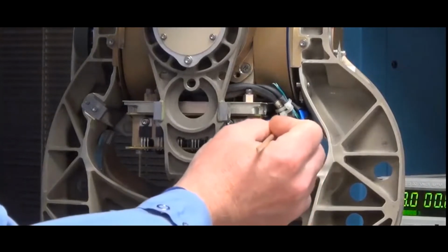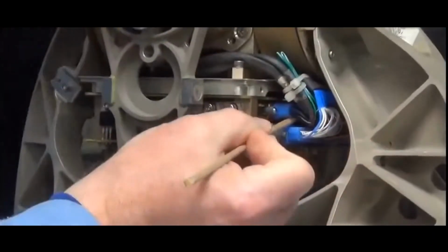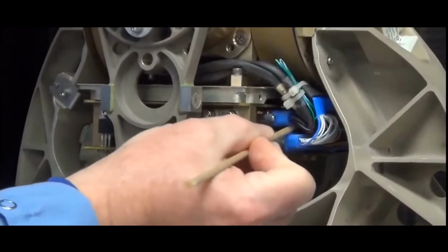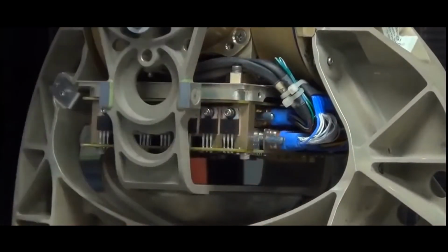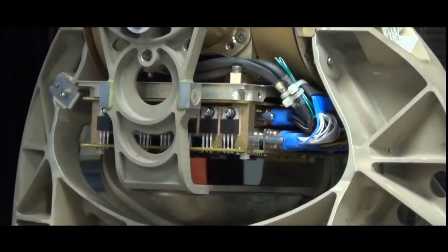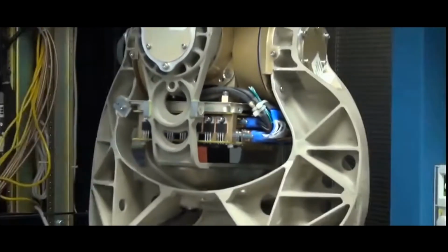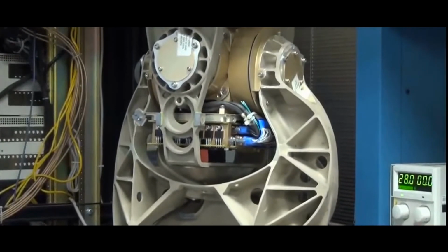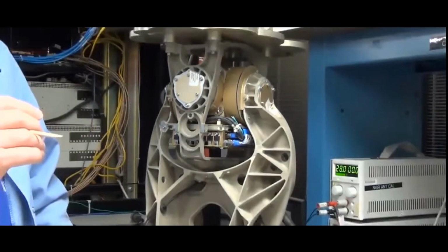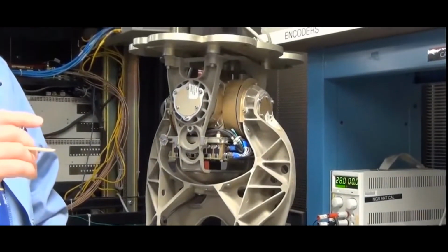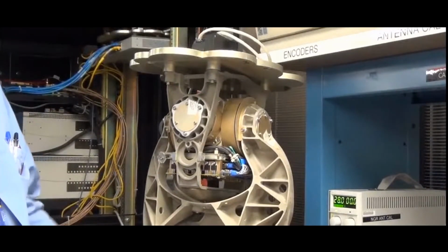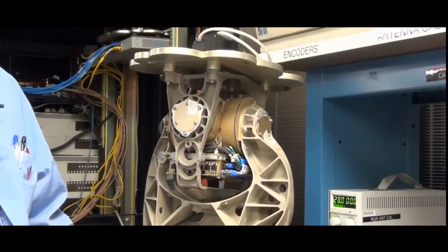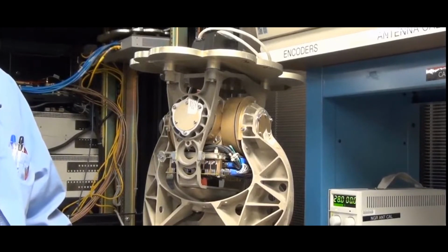So gently manipulate the wires and the connector. If you see it kind of move off on its own, and it just has to move slightly on its own. If you see it move once, you have a bad connector pin, and you need to replace them. And if you replace one, replace all the resolver pins, because we have found that if we have one, we usually have more than one. And that pretty much concludes troubleshooting and how to find a bad resolver pin.